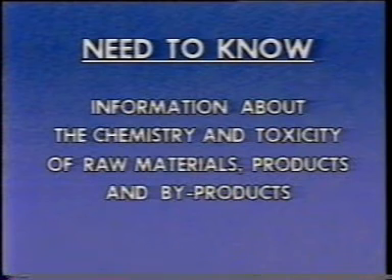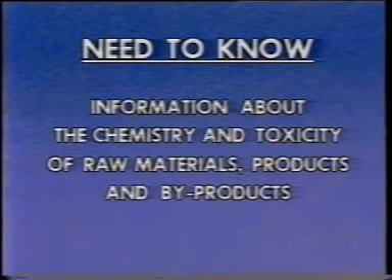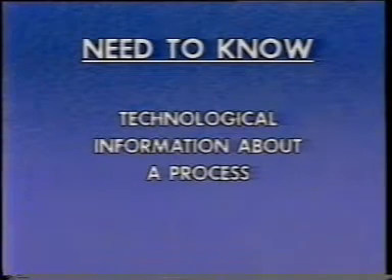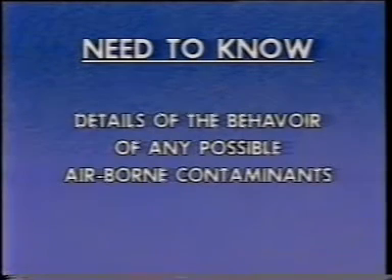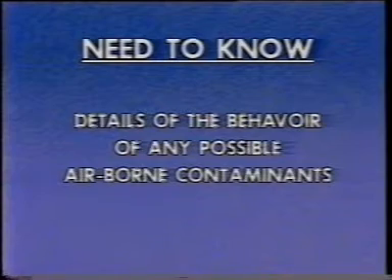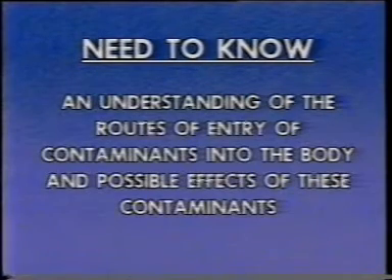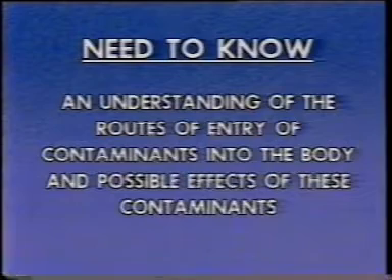In these less obvious situations, we may need to know some of the following. Information about the chemistry and toxicity of raw materials, products and byproducts. Technological information about a process. Details about the behaviour of any possible airborne contaminants. An understanding of the routes of entry of contaminants into the body and possible effects of these contaminants. The recognition of hazards is not as simple as may first appear. Experience and information are often the most important ingredients.